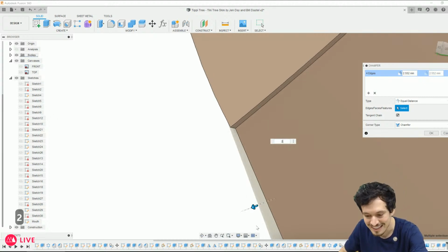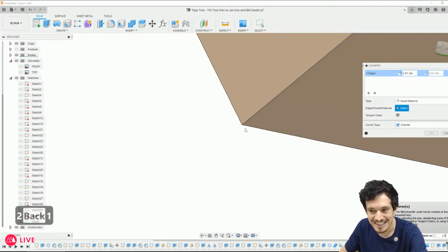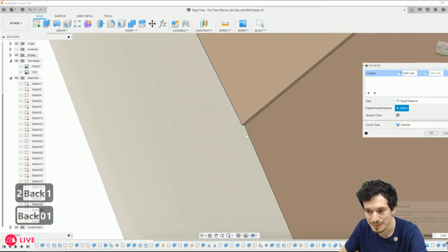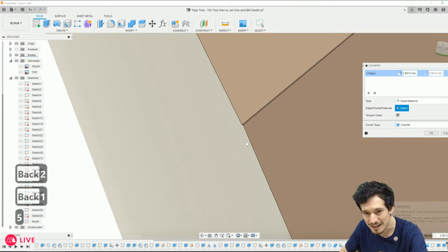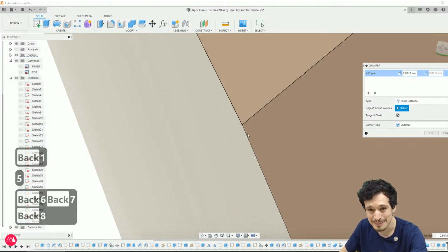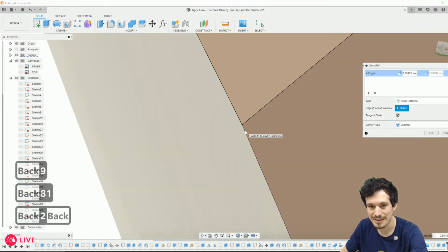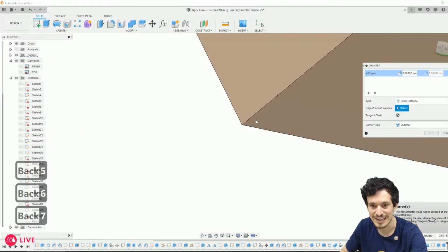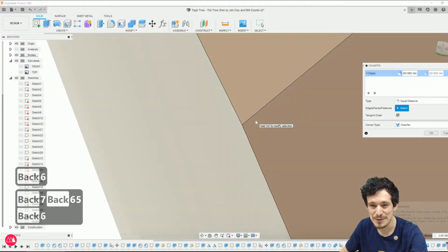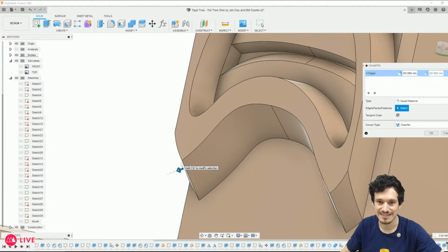Technically, there's a little overhang. Unless I find the exact value, I can just keep zooming in. I do this sometimes, like, oh, 0.61 doesn't work, but how about 0.601, 0.602 doesn't work, so 0.015. Just keep breaking down those decimals to get as close to a point as I can. This is also a little bit not the best practice, because if you try to fillet or chamfer that edge, Fusion's going to be very confused since it's not an actual edge. It's technically a very small face right there, but when you print it, that's an edge, right?